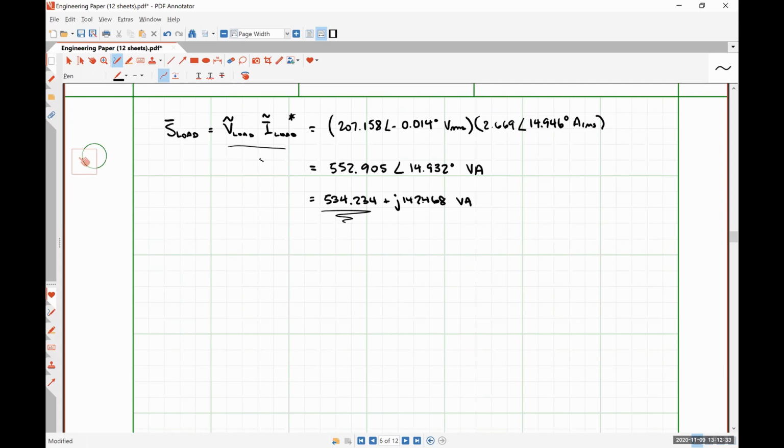You also get the reactive power. You get the apparent power. You have the means by which to calculate the power factor angle. All of that information is embedded in this one simple and single operation. Meaning, if you can convert between polar and rectangular in your calculator, you do not need to remember 4 or 5 different equations. It's just this one and telling your calculator how to format your answer, which in my mind is significantly easier than remembering all of these different ways.